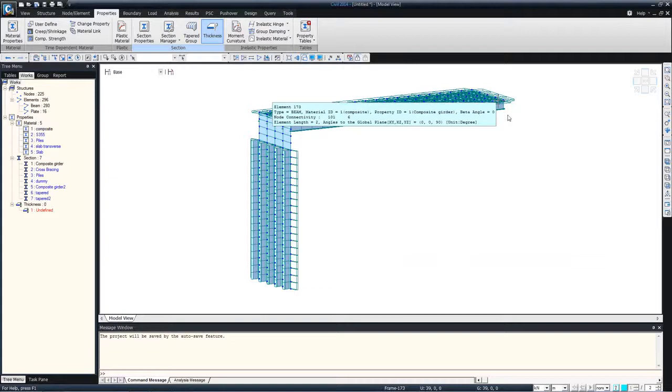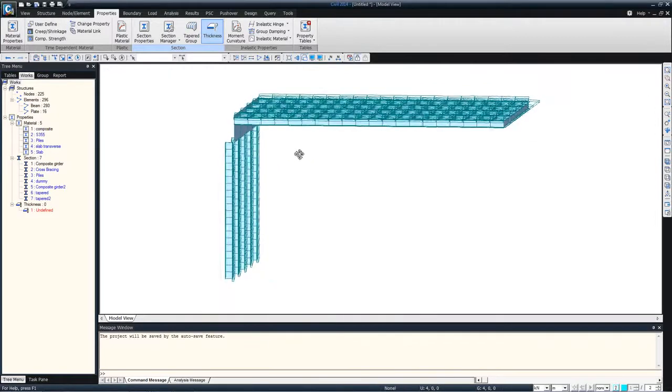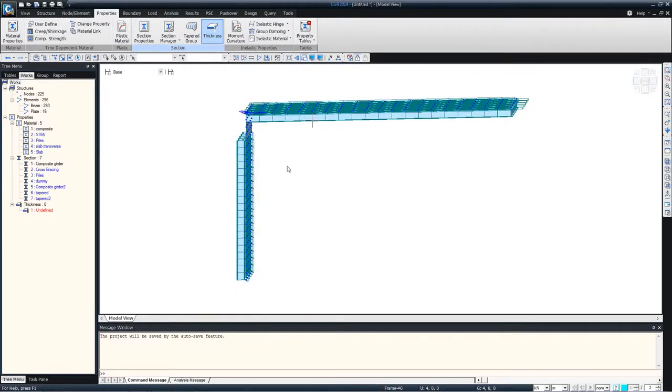There is no so-called geometry involved, and you will get to know the reason behind it, because the options available for geometry modeling are fairly simple within the software. So you can directly create the mesh as if it resembles geometry itself. I'll go through some curved geometries as well in this example. We'll look at curved bridges, and then I'll cover how to model a horizontally curved bridge. So I hope that answers your question, Riza.